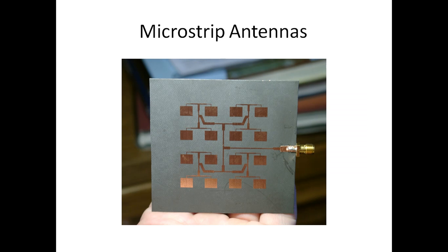Microstrip antennas are antennas where the microstrips are the device itself. It can be manufactured on small-scale volume used for research and experimentation. It can also be manufactured on a large-scale volume for commercial use. Also, in some cases, the dielectric substrate layer is replaced by a metal patch mounted above the ground plane called dielectric spacers. Antennas structured this way are less rugged but have wider bandwidth.